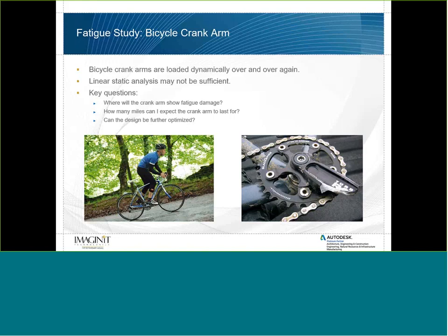And then we can take that data for cycles and determine how many miles or how many cycles I can expect my actual crank arm to last before I see any sort of damage or potential failure. From that, we can then decide, is this okay? Do we meet our design criteria? Or do we need to go back and make some design changes to improve the overall life of our design?